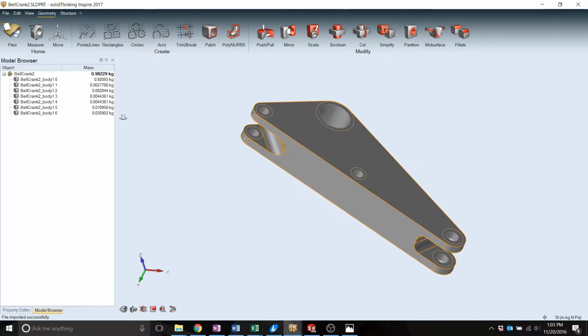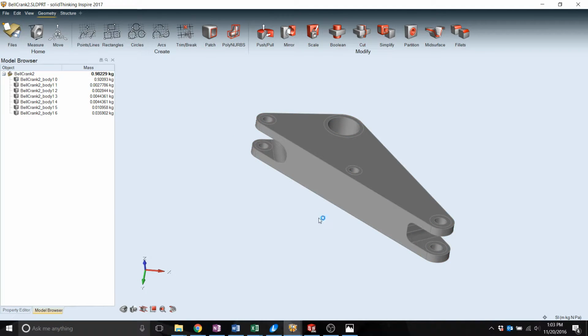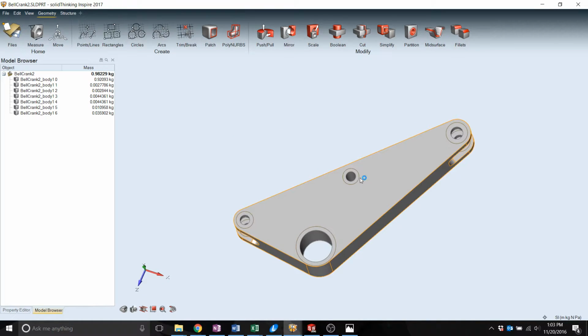Now you can see it did maintain the split lines for the different parts. As you can see, it only highlights that main body. To set that body as the design space, as we were talking about earlier, you just right click, go up to design space, and it changes your volume to an amber color to indicate that that's your design space.